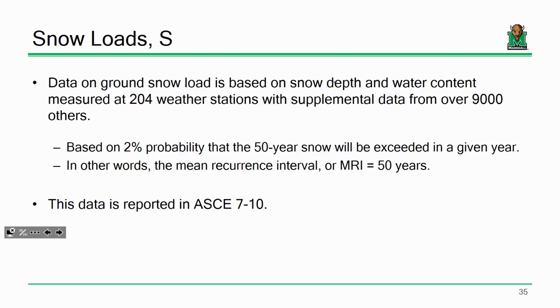So I'll try and make sure that I tell you if you're designing a beam whether or not the load is already reduced or not. In other words, if live load reduction's already been applied, you don't need to go through and do it again. So sound reasonable? Okay. All right.